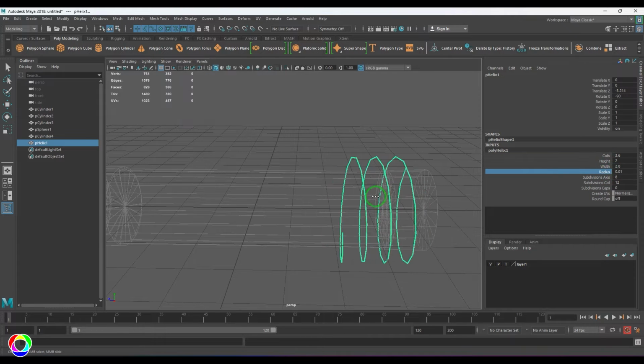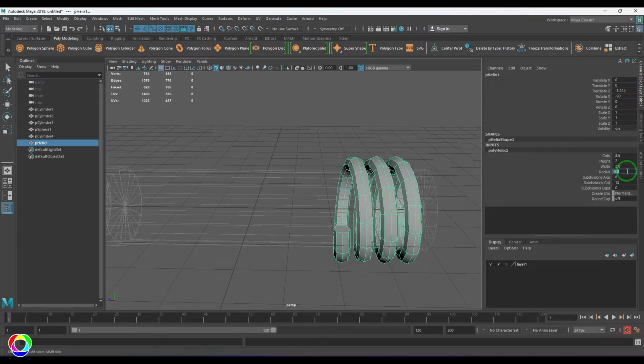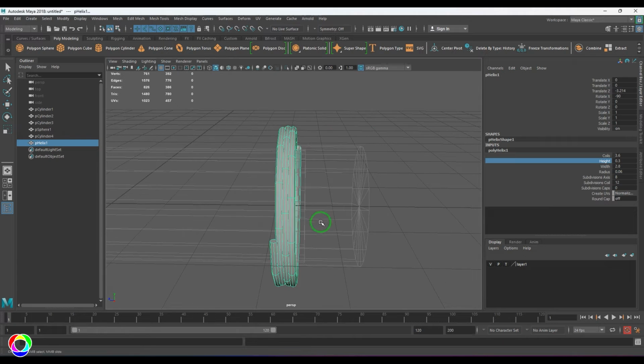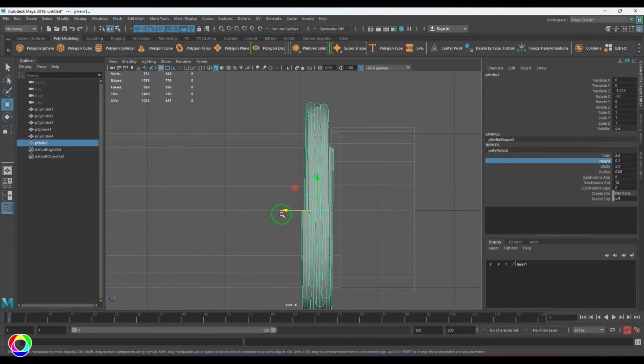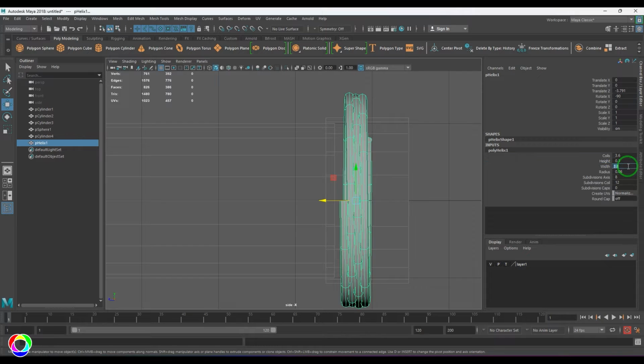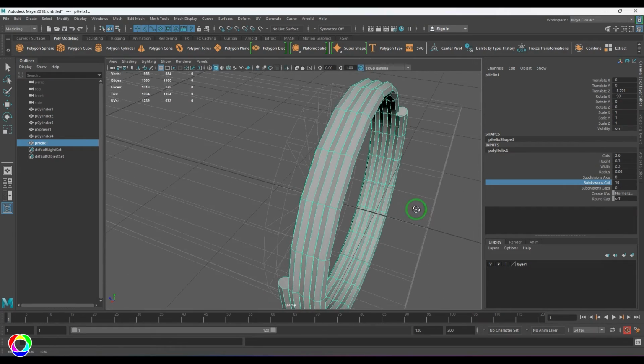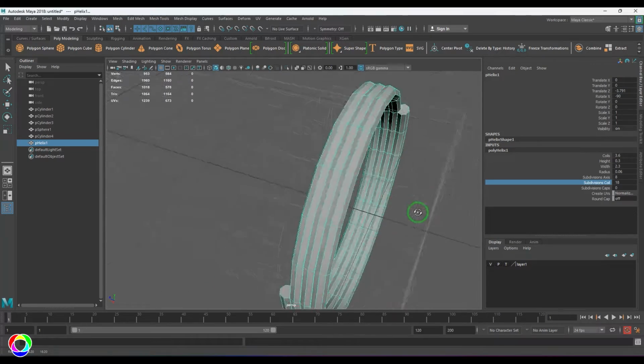and we have the radius option. I'll put a radius of 0.06 and then reduce the height there. Okay, I'll just move this one here, and then we have the width. I'm going to adjust it to the size like that, and I'm going to increase the coils. Okay, now 18 coils is actually giving me the perfect alignment there. Once that is achieved, okay, I need to delete the cap.